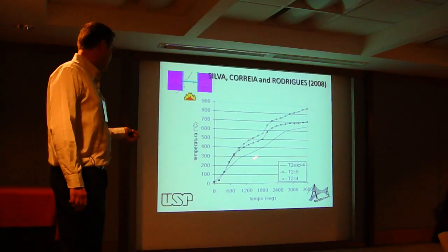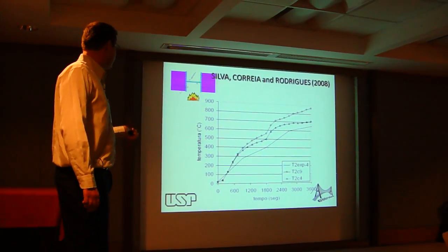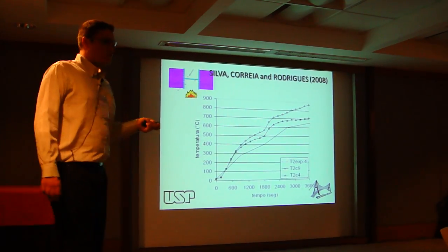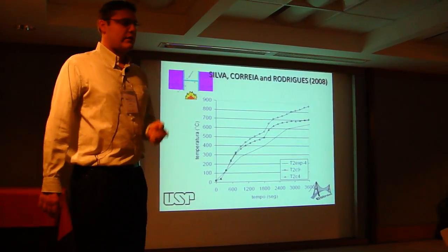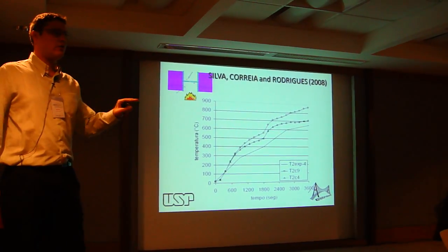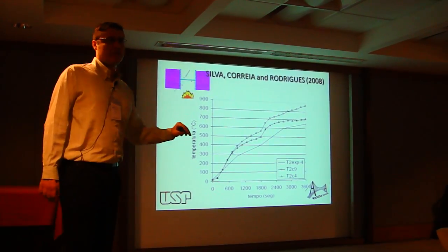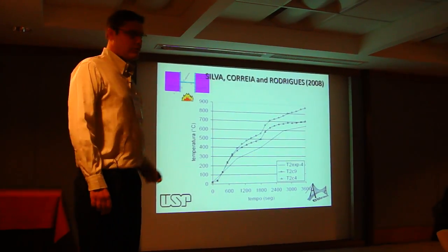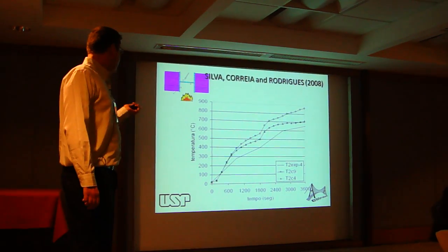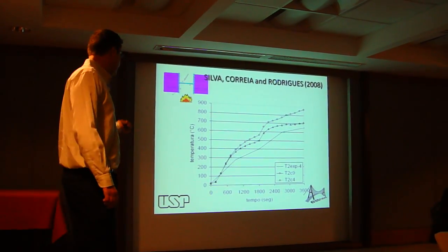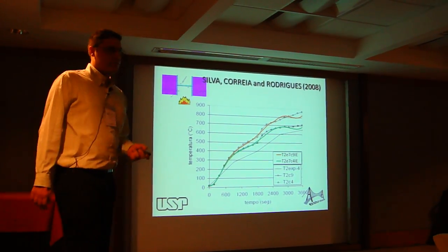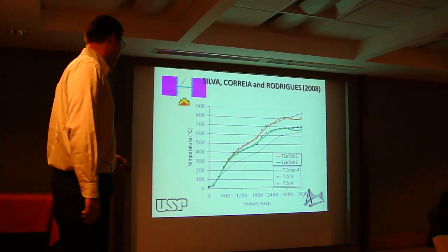The solid line is the result for the pointed node. And the other two curves are from a numerical analysis using SuperTempCalc, considering the two ways of heat loss preconized by the Eurocode 1. The analysis was done using ANSYS, and we can reproduce these results satisfactorily.